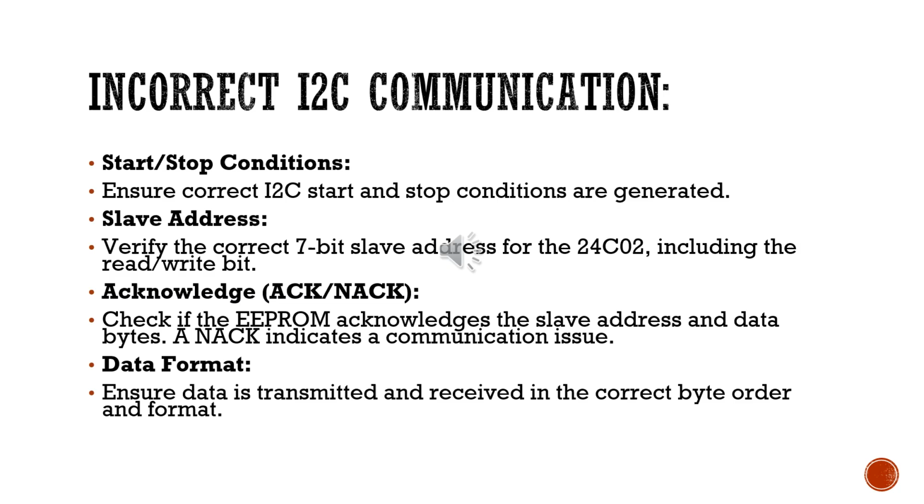3. Acknowledge. If the EEPROM acknowledges the slave address and the data byte; a NACK indicates a communication issue. 4. Data format. Ensure data is transmitted and received in the correct byte order and format.